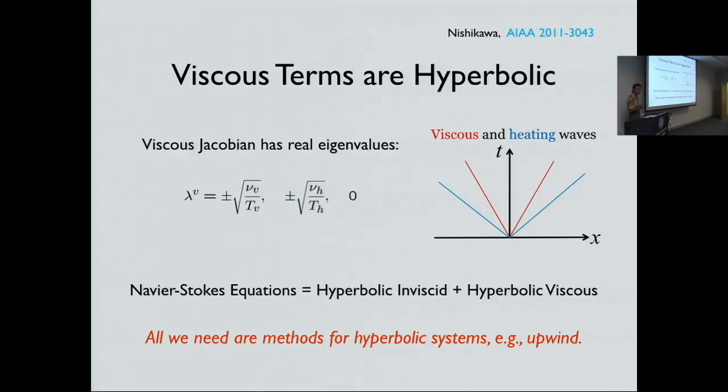Yeah. So if there were a bulk viscosity, that zero would become a third wave, a third pair of waves? Bulk viscosity would not be a... No, it's that there are zero viscous terms in the continuity equation. The bulk viscosity is still going to affect the momentum equations. Yes, and the energy equation. Okay. Yeah, if you have species transport equations, species transport would have it, and that's a whole other list of things. That's another continuity. Right. So continuity doesn't have a viscous term.